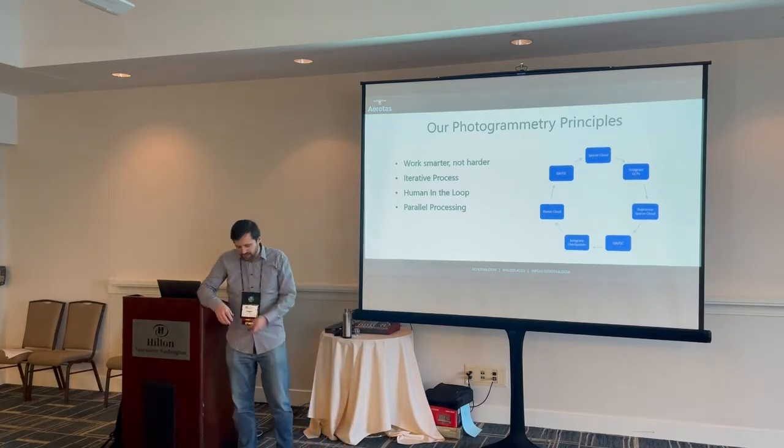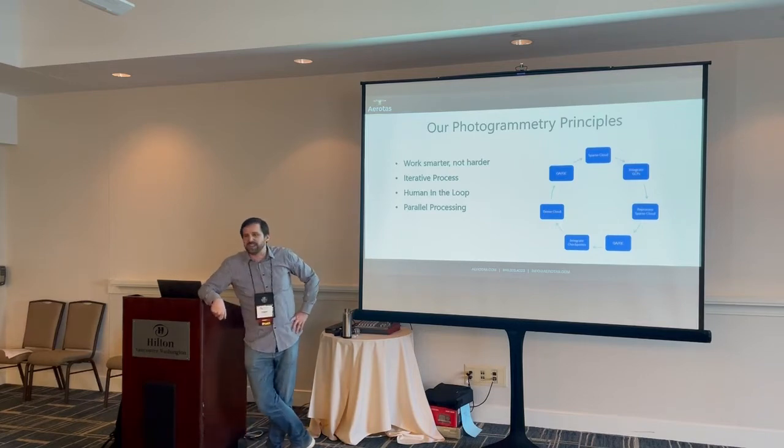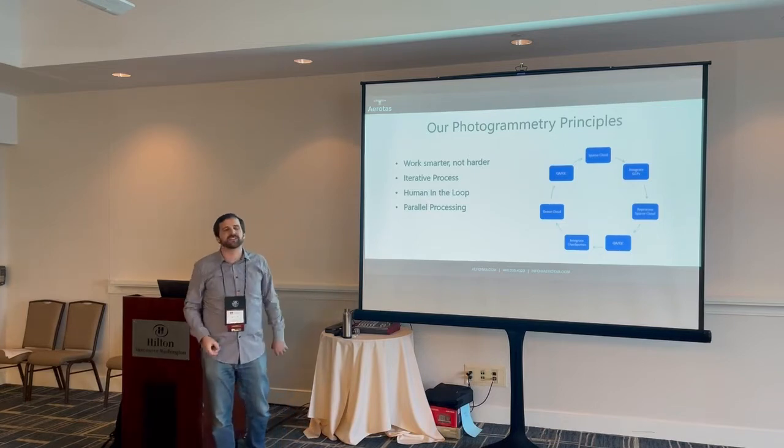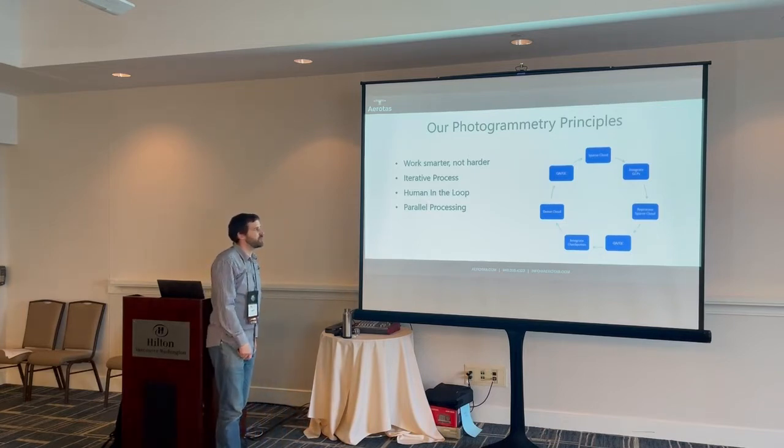And that is because every project is going to be unique, whether it was flown with changing lighting conditions over multiple days, the accuracy of the drone, heck, even the weather can impact the exact camera calibration parameters. If the temperature changes too much, the slight change in the camera lens is enough that we can actually detect that on a photogrammetry level.